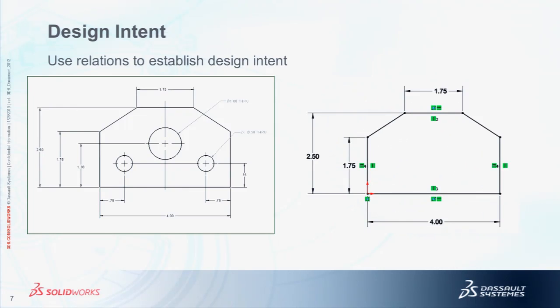I would like to say this would be the first sketch. Now, here we start talking about a couple of different things, design intent, as well as features. What the students are going to want to do is make a sketch, put 3 circles on there, and extrude the whole thing. And I'm like, what do you got? You got one extrusion. No, let's stop and think about what this thing is. There's actually, I would say, at least 3 features to this part.